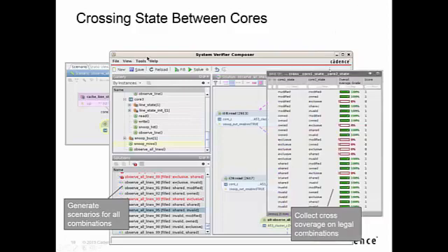And then it can give you a during-generation coverage view of, okay, the tests that I'm going to generate are going to give you this kind of coverage. And it'll highlight the areas where illegal state combinations are shown, and obviously shown as zero coverage. Those can then be removed as unreachable once you've analyzed them and determined that they are, in fact, illegal and uninteresting.